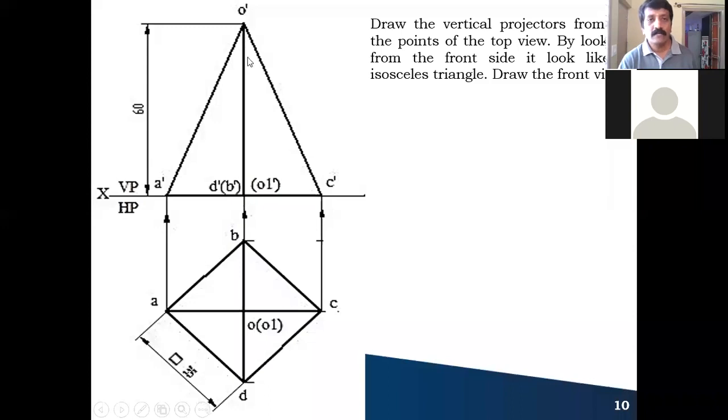Here, why am I drawing a visible edge? Because one of the edges will coincide on this axis. So let me give you this information also. Whenever visible edge and hidden edges coincide on the same line, we have to give importance to the visible edge. Even if I draw the dotted line here, I cannot see that. In this case, the axis line is coinciding with this line. Even if I draw the axis line here, the visible edge continuous line is already there. I cannot see that, so the axis is there, but I cannot represent it.